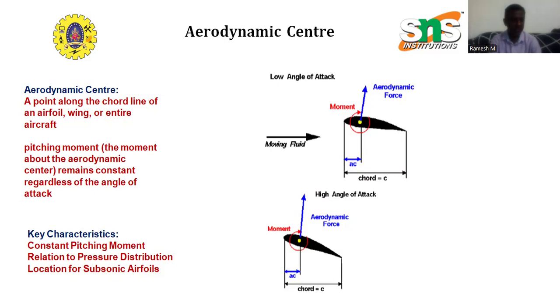With the camber, an angle of attack can be determined for which the airfoil produces no lift but the moment is still present. For rectangular wings, the wing aerodynamic center is the same as the airfoil aerodynamic center. But for wings with some other planform, called a triangular or a trapezoidal or compound planform, we have to find the mean aerodynamic center, which is the average for the whole wing.